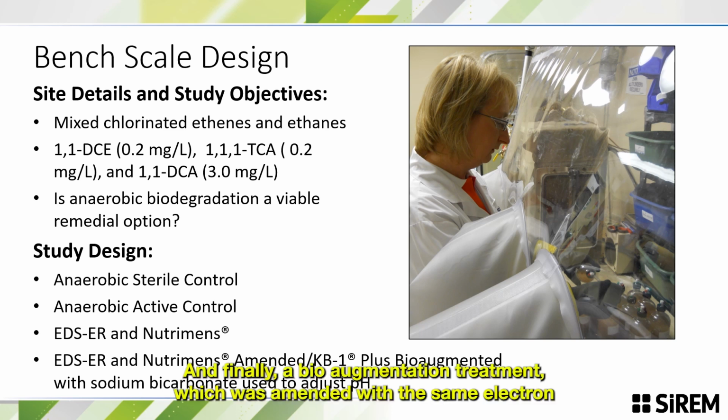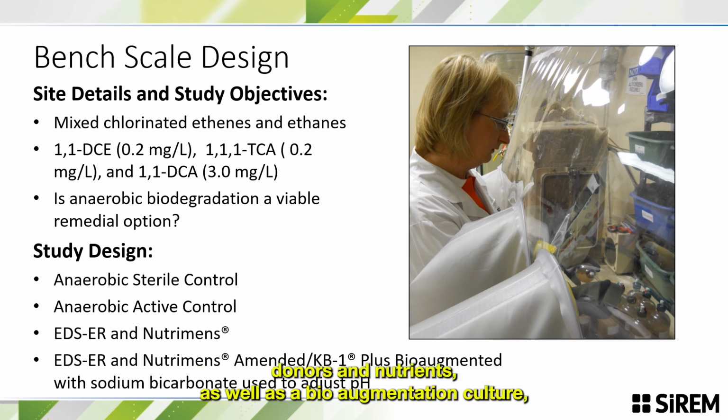And finally, a bioaugmentation treatment, which was amended with the same electron donors and nutrients, as well as a bioaugmentation culture, in this case KB1+, that contained many bacteria responsible for the anaerobic degradation of these chlorinated solvents. Additionally, sodium bicarbonate was used in this site to adjust the pH as the pH changed over the course of the study.